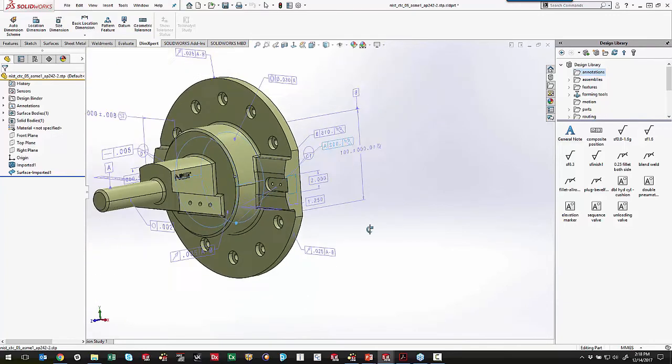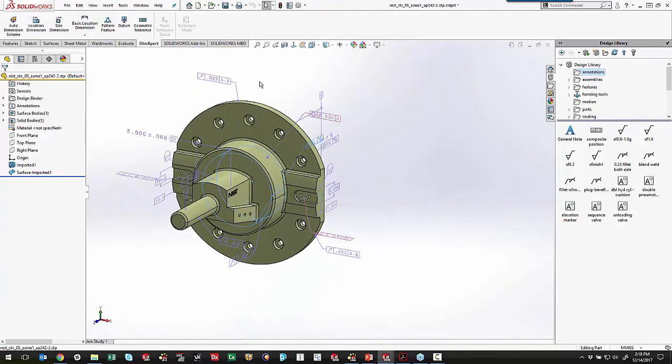Okay, so being able to bring in this step file with the PMI information all pulled in could be a nice way to help with the manufacturing process on down the road, and not have to provide the native SOLIDWORKS file, but a neutral file format that the people can use to machine off of. Okay, it's all about giving information to the people down the line.